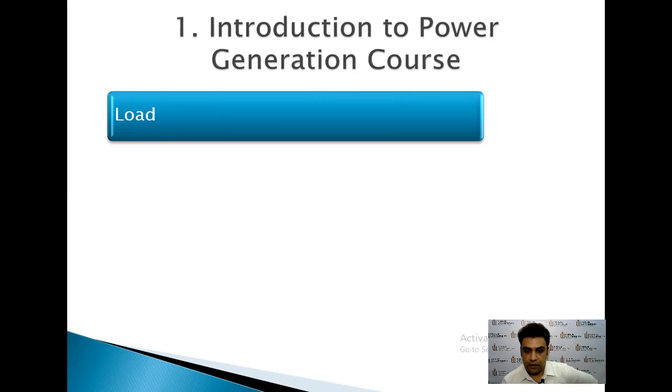And not only watching the history, but we also apply some other factors like survey. We do survey of industry, that what's their plan after 5 years. So after that, I can know the future load, what will be my load after 5 years, 10 years, and according to that, I plan my installation of a power station, so that we must meet the load. The basic requirement of power generation is that we must meet the load.